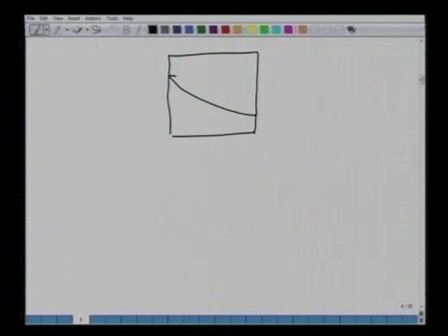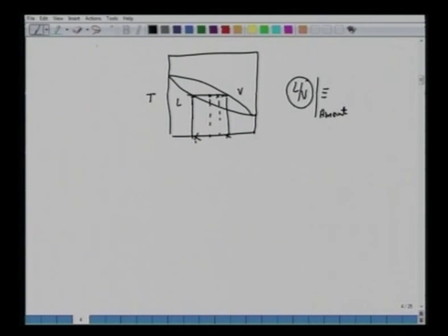So we have L and V. Choose this temperature, and you have the vapor phase and liquid phase compositions fixed. Or you start with some mixed feed here, and at this temperature allow them to come to equilibrium, and this is fixed here. I choose another feed in some batch experiment, allow them to settle, and I get the same L and V. It's only the amount of L and V that will be different, depending upon the ratios of the two segments across this mixture point M. So we have the same situation here.